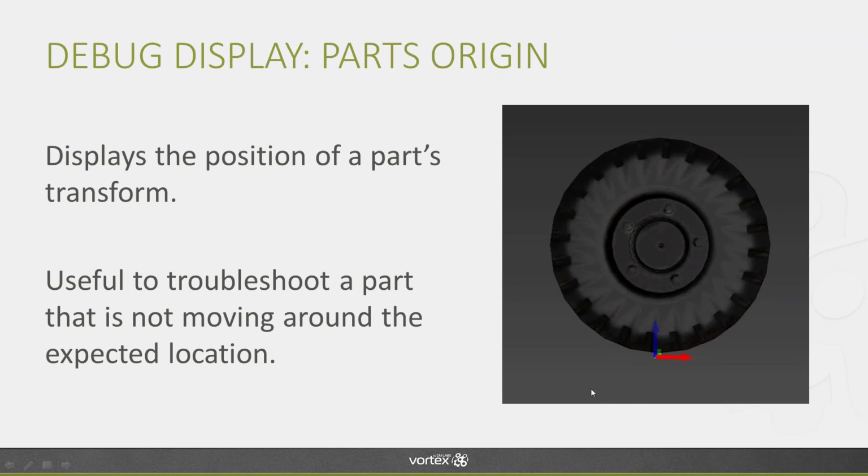You could look at the Parse Origin, figure out that, okay, I need either an offset constraint or I need to move my transform location. And that provides you with the knowledge you need to figure out the proper way to fix your issue. So with a center transform like this, if we had our constraints set to the transform location, it would work as expected and rotate around its center.